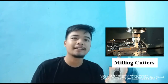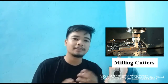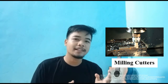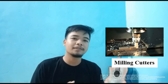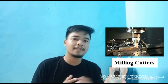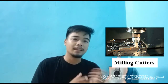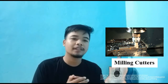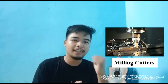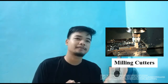1. Milling cutter. There are a lot of cutting tools used in milling, such as the cutter named end mill. End mills have special cutting surfaces on their end surface so that they can be plunged into the workpiece like drilling. These also have extended cutting surfaces on each side for the purpose of peripheral milling. The milling cutters have a small radius at the end corner. The milling cutters are made from highly resistant material that is durable and produces less friction.